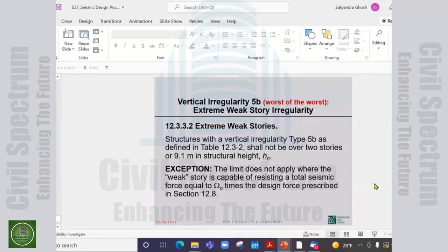This I did not say, I should have said. You can ignore the limit C sub u T sub a. You can directly use the period that you computed from eigenvalue analysis. The code doesn't care, because I want to explain this. So the stiffness will be, if you use approximate period, the approximate period is shorter than the real period, so you are taking a stiffer building.